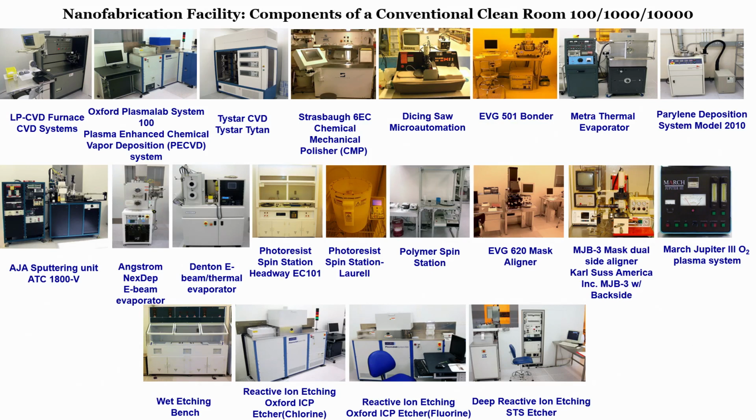We will see next an E-beam evaporator. It is an electron beam evaporator, again to deposit metal using the E-beam technique. The advantage of E-beam, or why we have to go for E-beam over a thermal evaporator, is that with E-beam you can deposit a metal which has a high melting point, while the thermal evaporator has a drawback: if the melting point of the metal is too high, you cannot thermally evaporate it. We will discuss what exactly that means when we discuss the thermal evaporator.